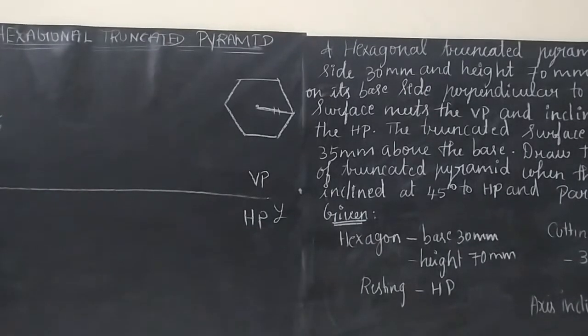Normally what they are used to do is, they draw an imaginary line, measure O and D, cut an arc, take this to the reference line, and draw a true slant edge. Whatever you get will be the true slant edge, and in that slant edge you will be getting all the points. But I haven't done it here because we already have so many points, and it would just get confusing. So I'm not going to that process.